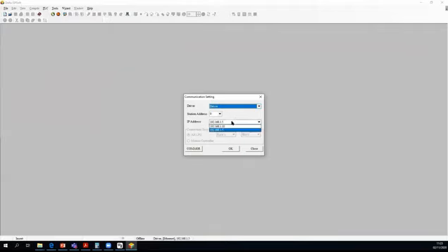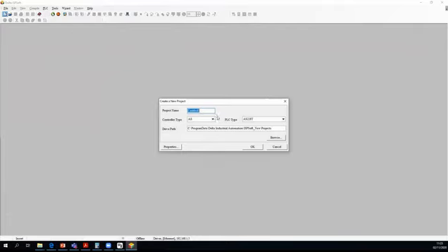So I will open ISPsoft. I will select here the PLC. So this is the driver, which I just created. And this is the IP address of the AS200 PLC. So I will connect to it. I will use that as a connection. And I'll create a new project. So AS228T, which is also the PLC that I'm using.